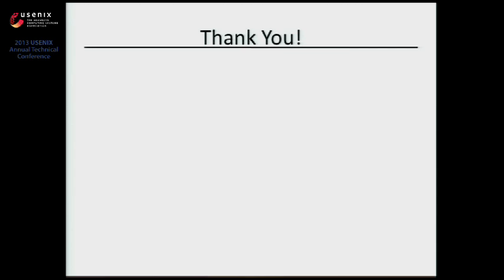Right. So we investigated how far you can push the small packet interface. We investigated that if we go one cache line size or even a couple of cache line sizes, you can communicate this directly. You can just have the CPU write out to the NIC. But even at 1,500 bytes, that's not really feasible anymore because you're wasting too much CPU throughput. So we went back to a DMA interface. So for jumbo frames, it would just be a bigger DMA read, basically. Okay, thank you. Thanks.